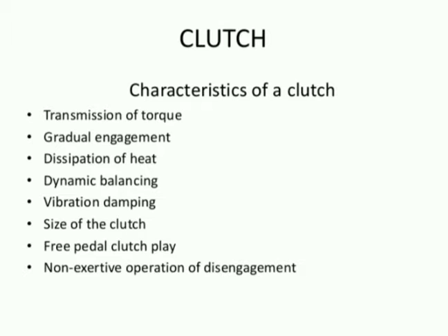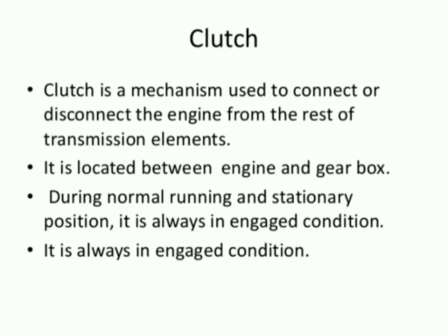Then what are the characteristics of a clutch? First one is transmission of torque, then second one is gradual engagement, dissipation of heat, dynamic balancing, vibration damping, size of clutch, free pedal play, non-exertive operation of disengagement.